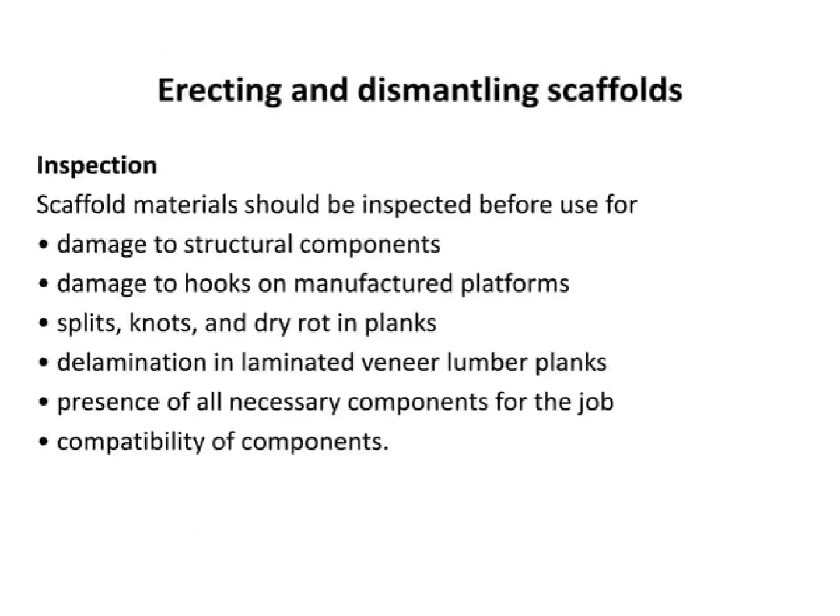To safely erect and dismantle scaffolds, inspect the materials used. Look for any damage to structural components, such as hooks on manufactured platforms, splits, knots, and dry rot in planks, delamination in laminated veneer lumber planks, and confirm all necessary components for the job are compatible.